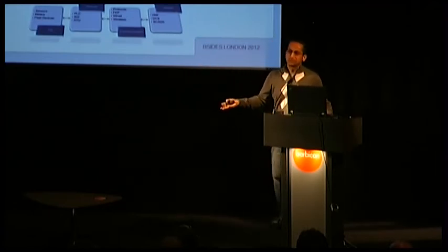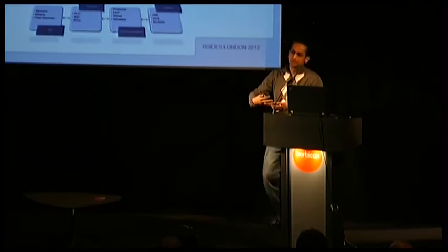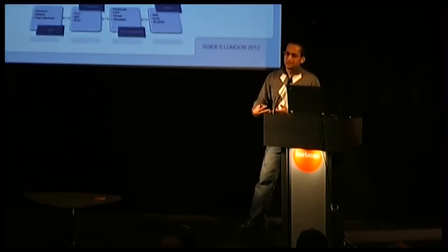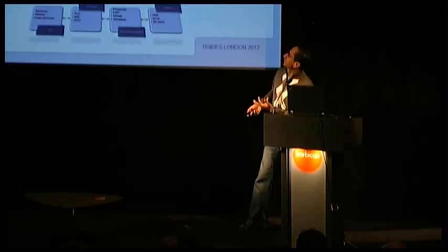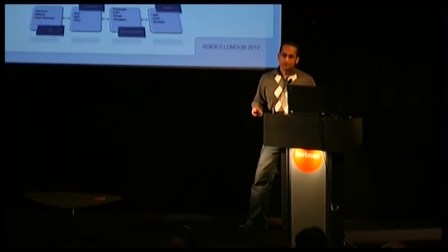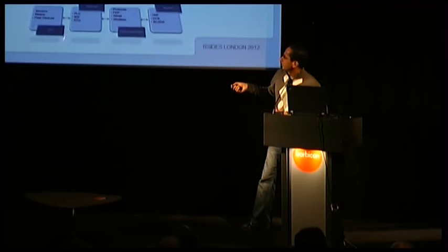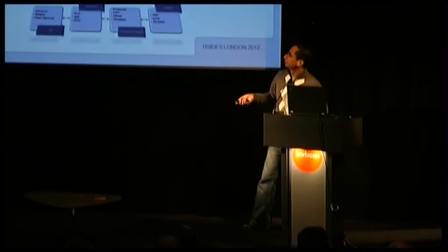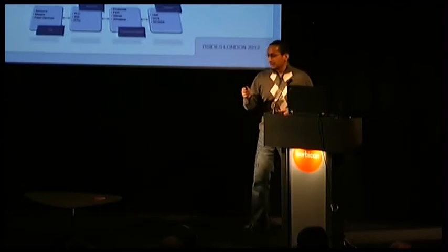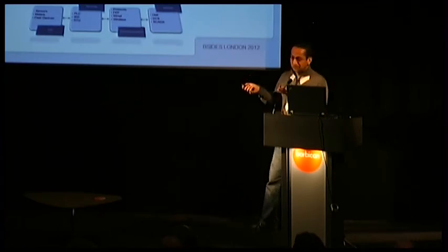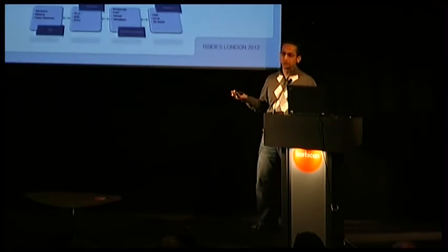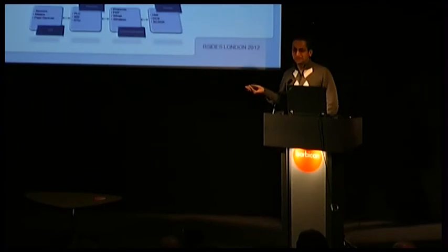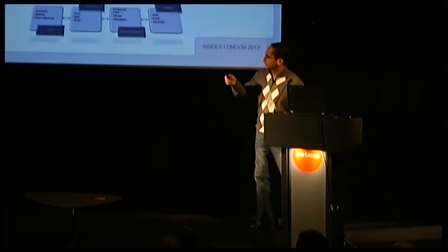Or if it's an industrial control system, it may not be thousands of miles away. It could be inside your organization, on some conveyor belts or things like that. They monitor for these parameters and convert them into discrete or analog signals. Then there is a two-way communication between the data acquisition component and the data conversion component. Data conversion includes basically PLCs, like the ones that we saw earlier. PLCs are programmable logic controllers, IEDs, or intelligent electronic devices, or remote terminal units.